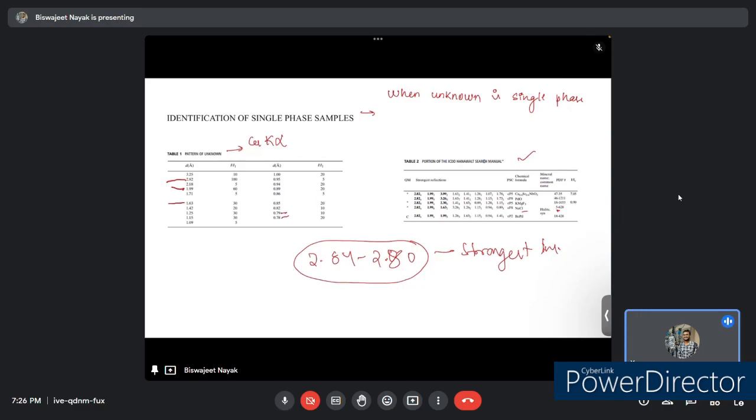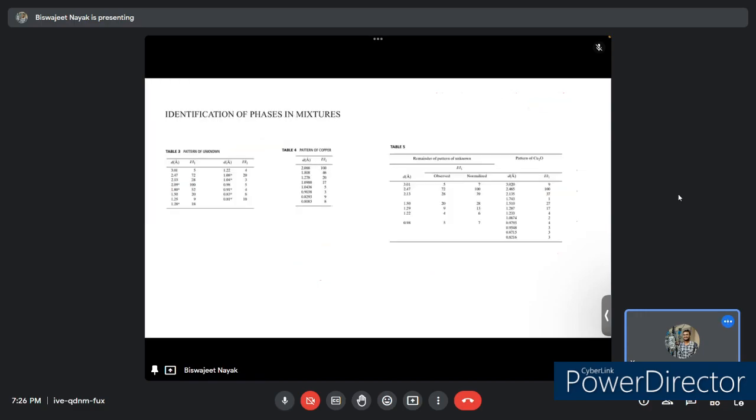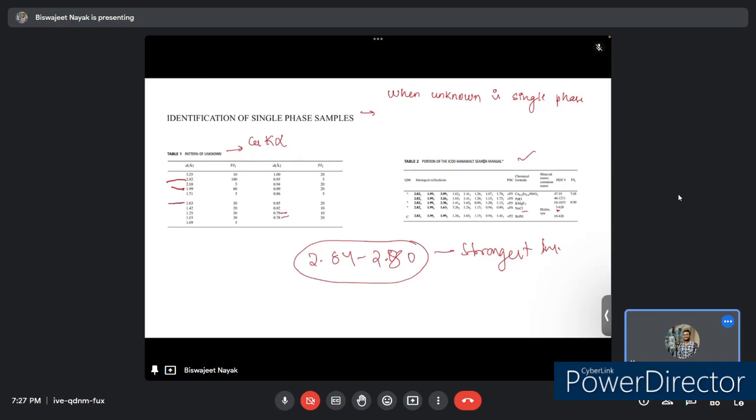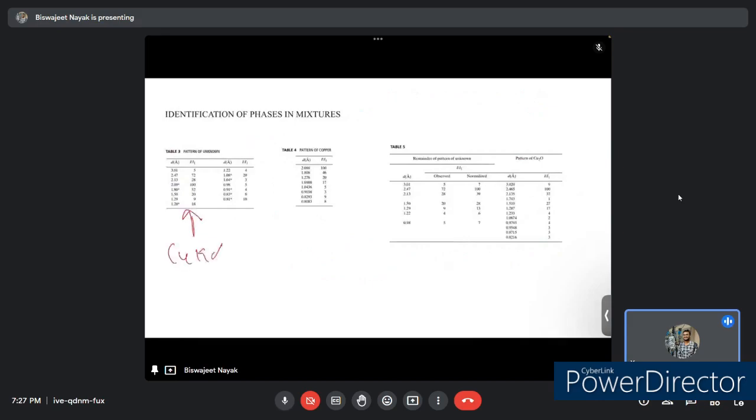A few unexplained weak lines are often assumed to be due to unknown impurity. The identification of the main constituent is then somewhat tentative, and depends on how experienced we are. Because small d spacings correspond to back reflection lines, they are measured with greater precision than larger d spacings. Spacings smaller than 1 angstrom should therefore be computed to the nearest 0.001 angstrom rather than 0.01 angstrom. That much precision we should keep while measuring.